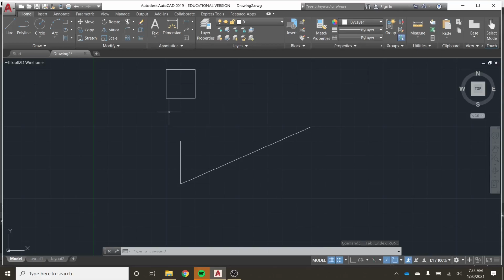Okay, so now I want to draw a line, and I'm going to show you the different icons that are going to show up for those different positions when I'm trying to draw a line to connect to this box. So I'm going to come up here, and I still have my snap to grid, which is good. I'm going to start a line here, and I want it to go, let's say, to the edge of the box. And if you notice the corner of the box there, it has a green square. That's a little icon that tells you that you're on a vertex of a box.